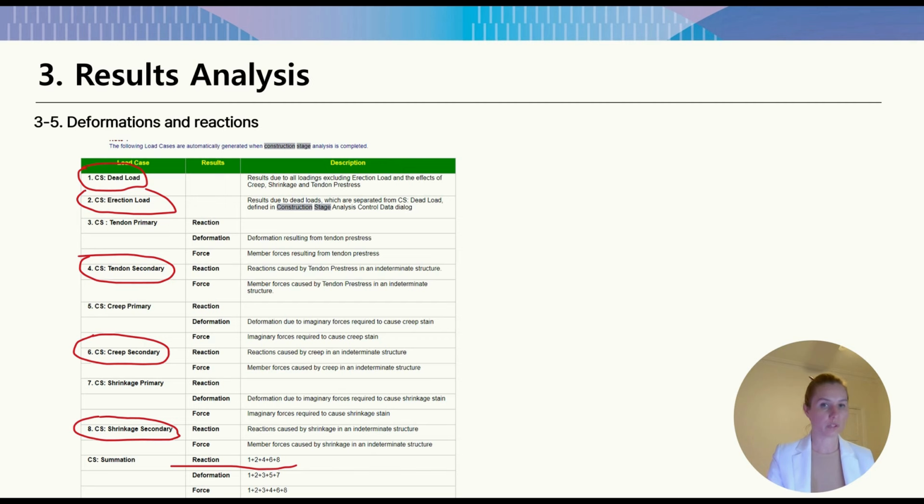In order to obtain the correct displacement in the deflection joints and bearings, it's necessary to calculate not only the displacements due to temperature, but also the deformations due to elastic shortening, creep, and shrinkage. These deformations tend to act in one direction, which we can see in the tab results, then deformations. I'll show.